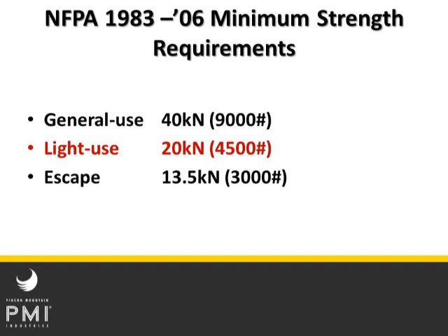So it gives you that 9,000 pounds on the general use rope, which for most people is a 1/2 inch rope. The standard actually allows it to be a little less than that, but I don't know that anybody's been able to build one that meets the 9,000 pounds yet and the elongation curves. It'll be interesting to see when and if that happens.